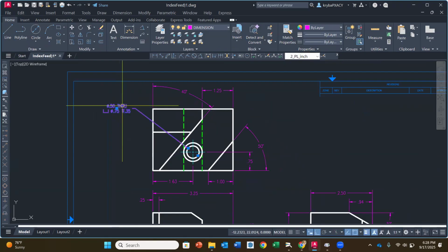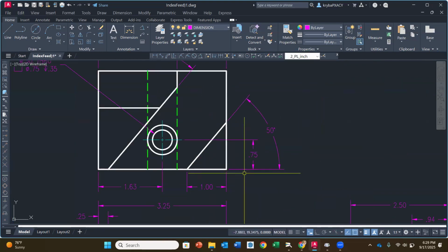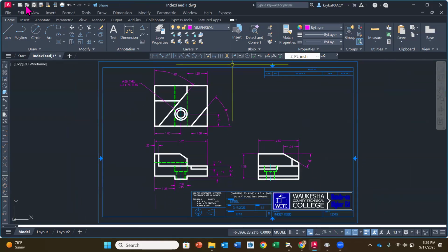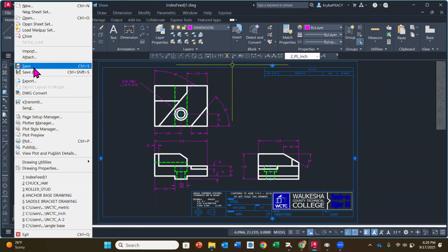If you need to move it, remember we never want it to be horizontal. We don't want it to be super vertical. Actually, I'm going to turn my ortho off. Where we're at is actually pretty good. So something like about that 30 to 60 degree angle for that leader. Okay, I'm going to zoom extents. Kind of look at my drawing. What do you think? Compare it to our guide.